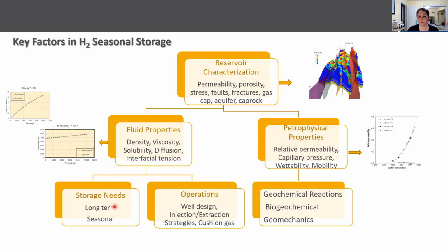And then we need to think about, is this a long-term storage or is it seasonal? Because the way you optimize it and you do your operations may change depending on the needs of the storage. You need to think about operations. How many wells do you want to have? What are the designs of the wells? What are the injection extraction strategies? And then do you want to use different cushion gas, for example?